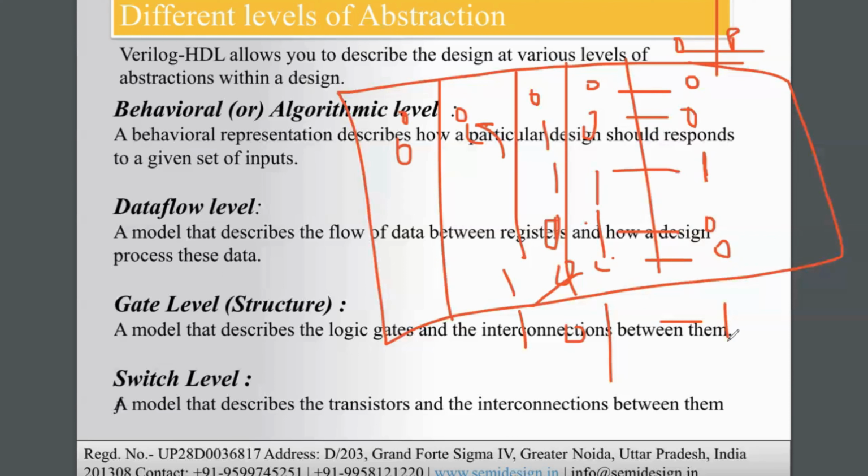So these are the rules you need to follow to design any digital circuit, whether it is combinational or sequential. You need to understand the problem statement first: what the inputs are, what the outputs are, and how many combinations it will generate. And if there are any control signals, like clock, reset or enable signals, you need to check accordingly.